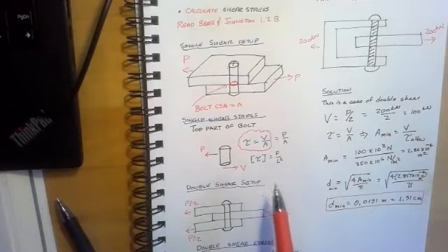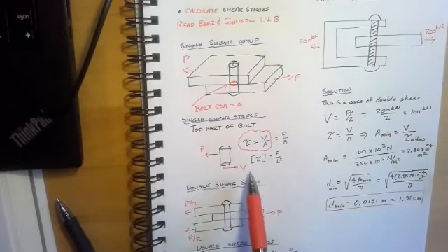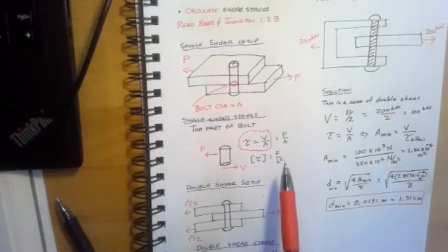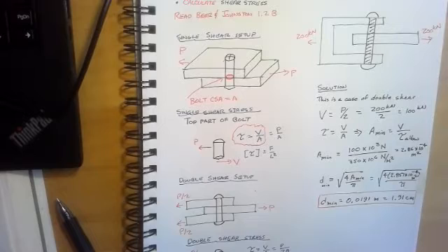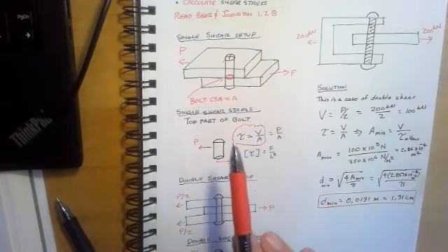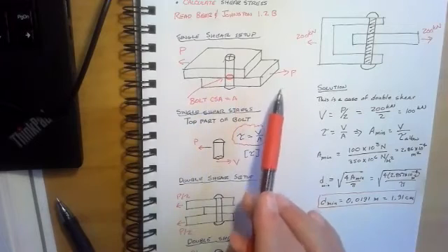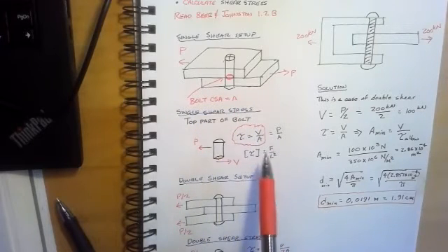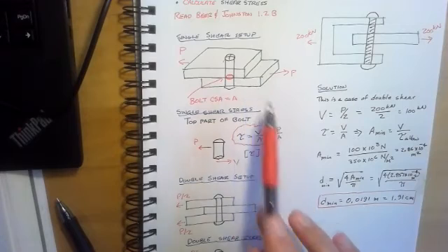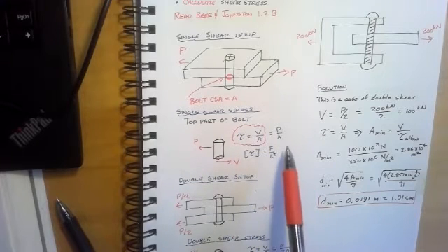Now, as before, when we were talking about normal stress, the units of shear stress are going to be force per unit length squared. And that would give us the same types of units: PSI, KSI, pascals, megapascals, gigapascals, whatever is appropriate for the stresses in a part. So for the case of the single shear bolt, we would have the shear stress given by the general equation, tau is equal to V over A. And in this case, the specific instance equals P over A.